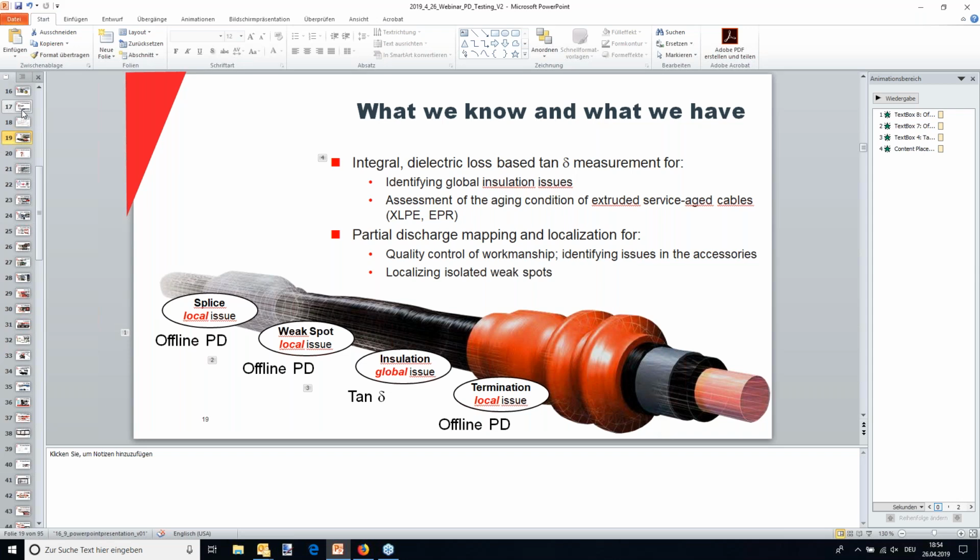Oh, thanks. So when we're testing on a cable spool, do we need to pre-lay the cable on the floor prior to testing for DAC tests, or could it be done while the cable's on the spool itself? Additionally, can we also use that to find a bad pilot in the cable, in addition to the LG and LL faults? Okay, so when you say pilot, I assume you mean the fiber optic in this case, something like that.